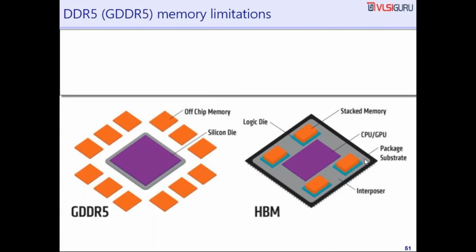So how it is done is, see, the black one you see is the package or the substrate. On that, we have something called an interposer. The interposer will have some kind of bumps. Bumps are some kind of pointed things where you can plug in whatever circuit you want, and then they get soldered, I mean, they get connected essentially.